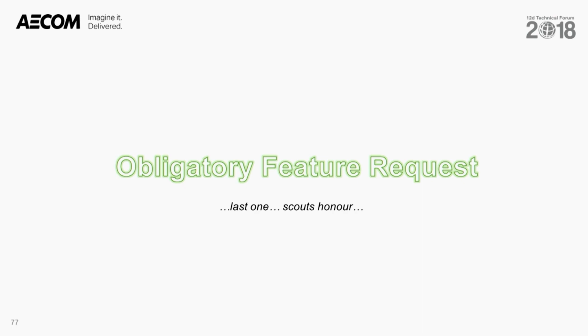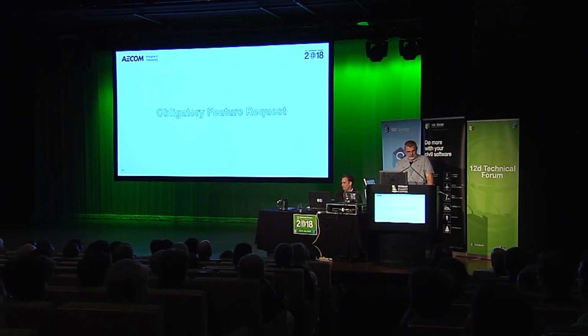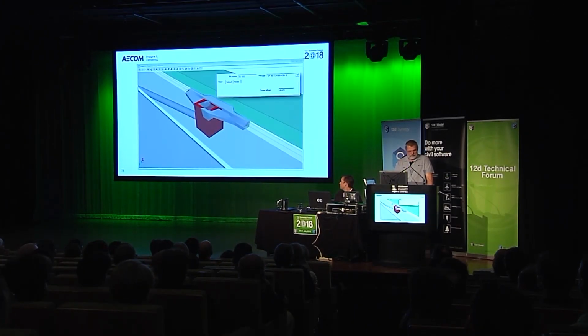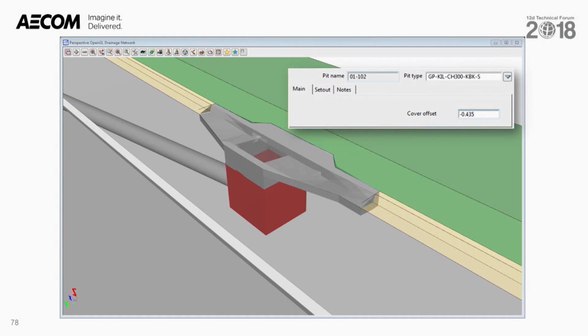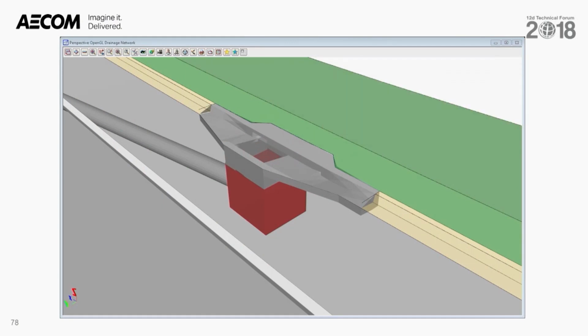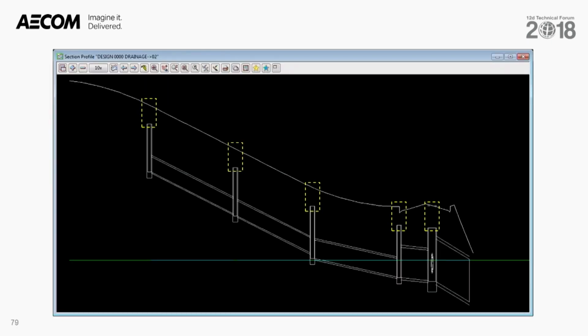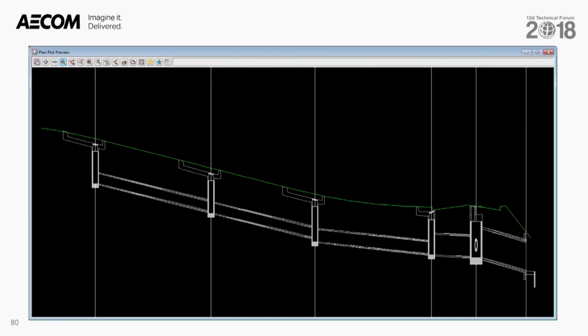What is needed though is the cover offset to be preset in the drainage.4d file for each structure type, which automatically trims the top of the chamber to the underside of the trimesh. Now, I haven't worn a drainage designer's anorak for more than a decade now, but I've been told that the setting does not impact on the hydraulic calculations. The truncation, however, does look a little strange in the profile view in drawings, but by converting the drainage model to trimeshes in a chain and adding them to your plot corridor models, you get a better looking result, especially if you plot the drainage network to a no plot color, so you only get the trimeshes shown.